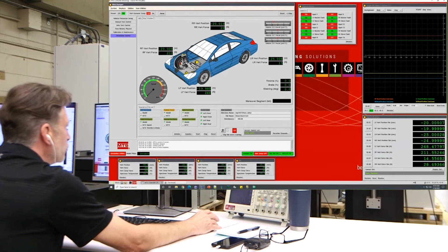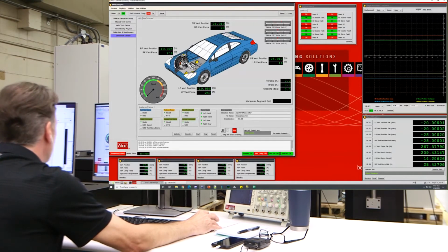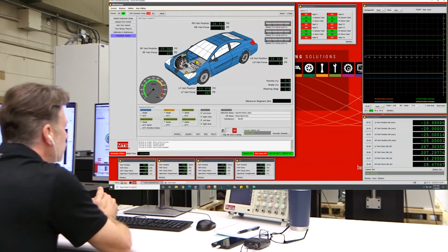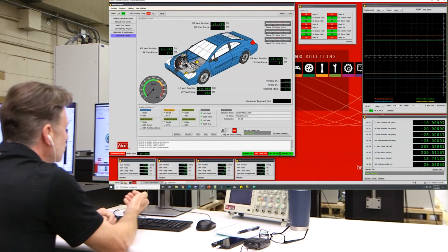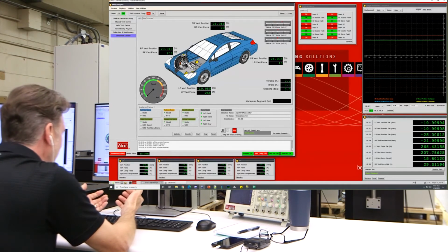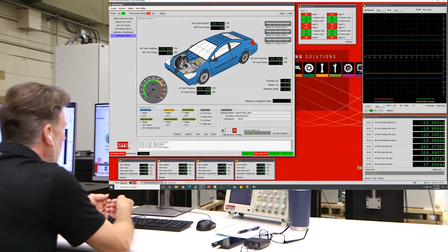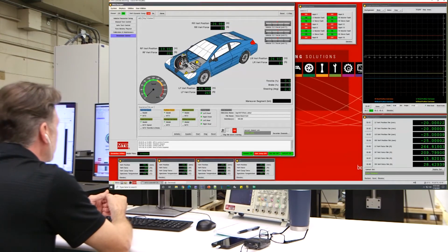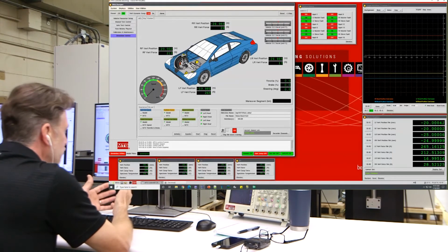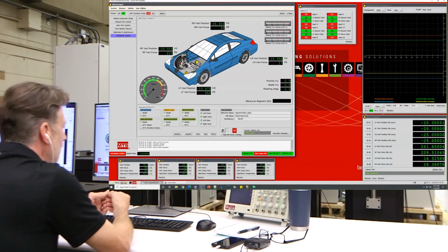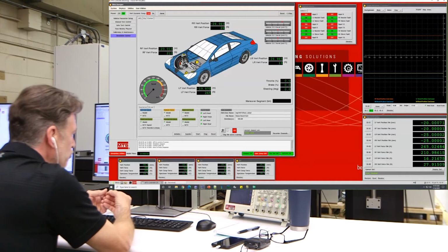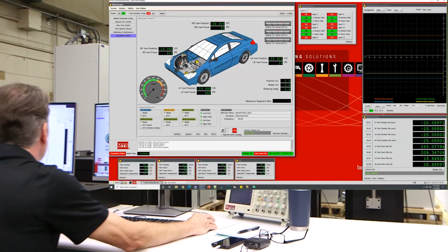Here we've got a special maneuver and a flag that holds that maneuver. We want to hold it in place because we've got the next step that is required, which is the equalize. In equalize, what we do is we take a look at what the physical system is set at and what the virtual system is set at. The physical position will likely be different than what the model is reporting for damper position because it's going to be based on spindle height or some other reference line within that simulation. We have to equalize those two components so that we can then make the command and feedback source switches, which are the buttons we have up here.